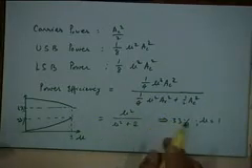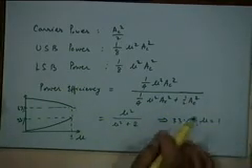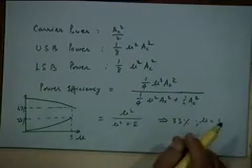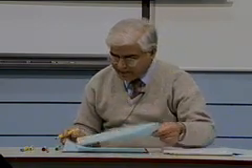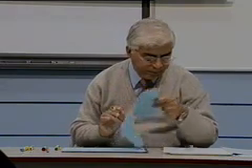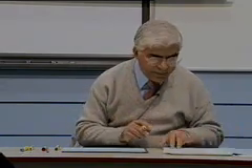This discussion we have carried out when the modulating signal was a pure sine wave, right. One can prove that for more general kinds of modulating waveforms, the power efficiency can be increased, but under no circumstances will it be more than 50%, like we discussed earlier. Okay.